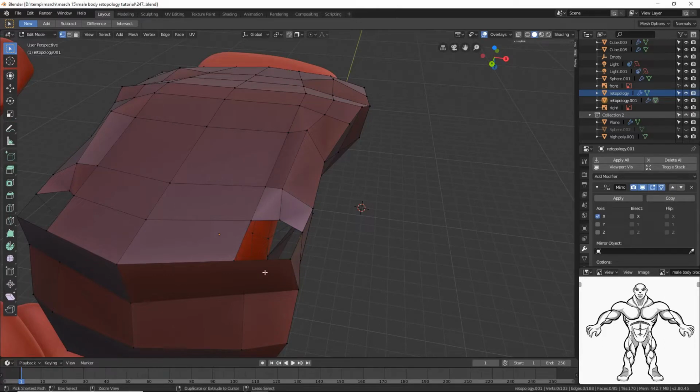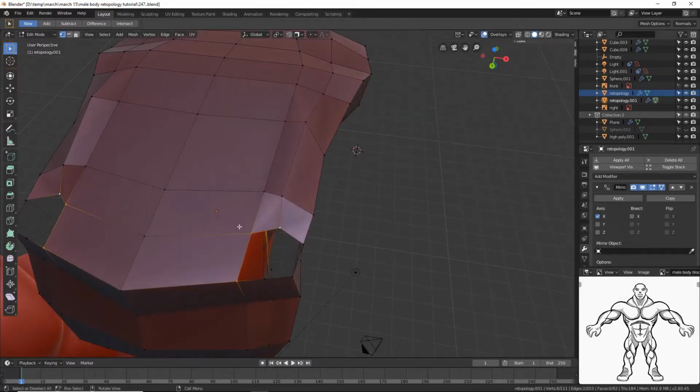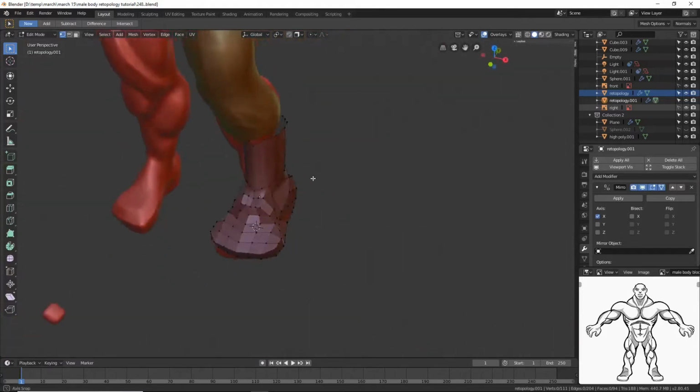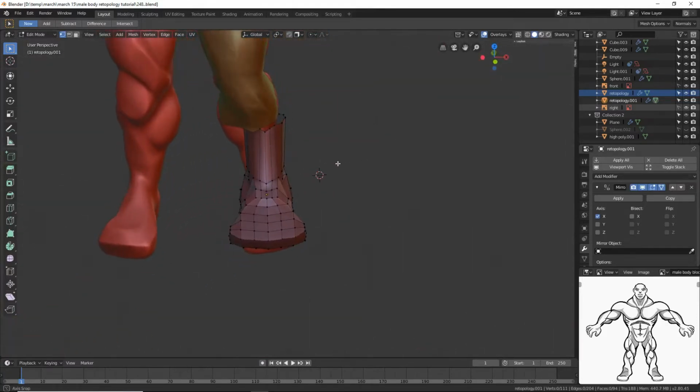Okay, I'm going to hover here, hold control, press R, left click once, left click a second time, left click here to deselect. I'm going to click here, hold shift. I select the vertex, I'm clicking again. Now I'm holding shift again. I'm going to press F to fill. I'm going to click here, hold shift. Then I'm going to press F to fill, then left click to deselect. I'm going to hold control as well as the middle mouse button to flip this back around.